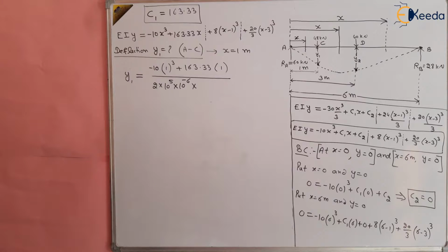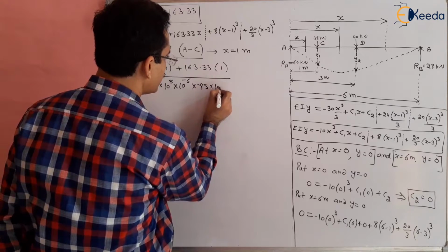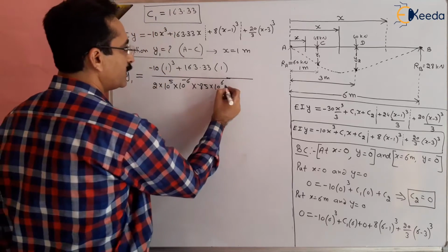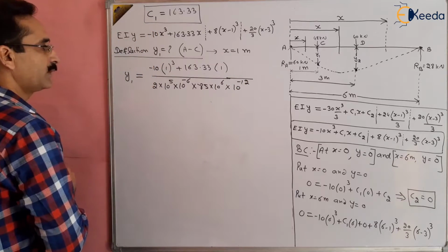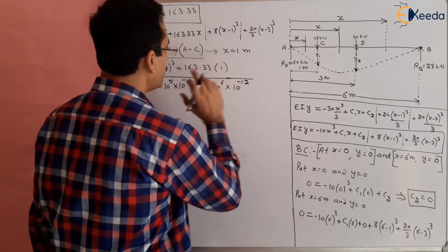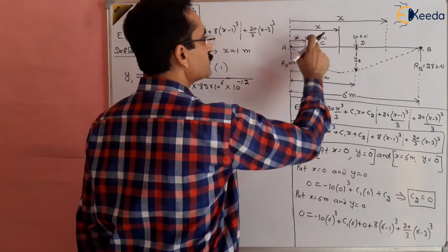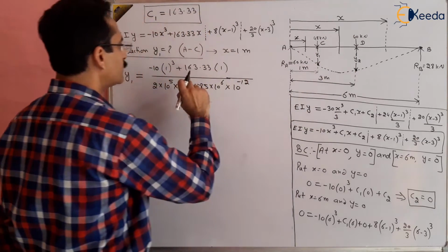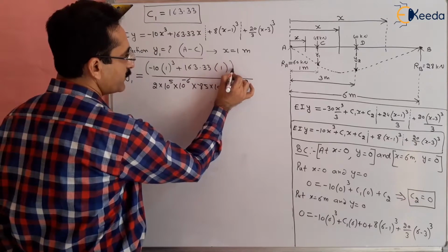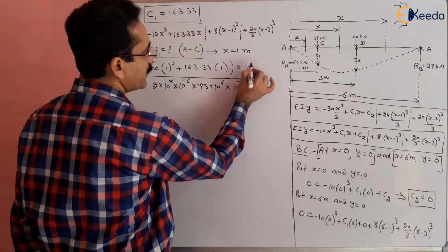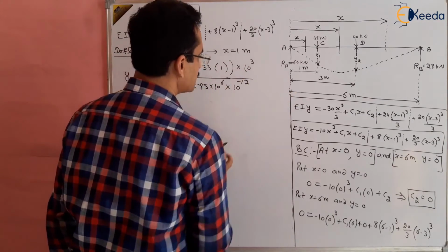So I is 85 multiplied by 10 power 6 millimeter to the power 4, so it will become 10 to the power minus 12, right? This much, but here the load was given in kilonewton, so that kilo should be replaced with 1000 to get the answer in SI unit. That's why I am multiplying it here by 10 power 3. The answer will come now in meters, right?